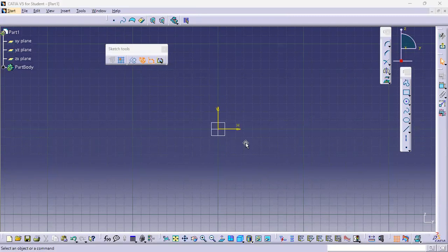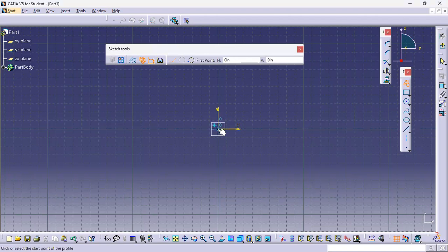I do have 3.5 width, so I'll pick line or polyline, and then pick this 0 0. You can see this is vertical, and that's the initial point. As you saw in the previous example in class, we have seen these polar and Cartesian expressions in either relative or absolute coordinate system. So this would be the absolute one.